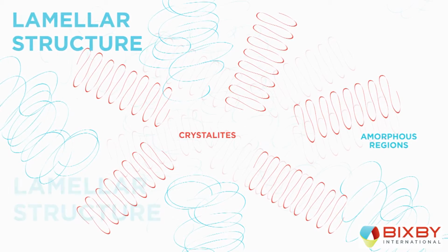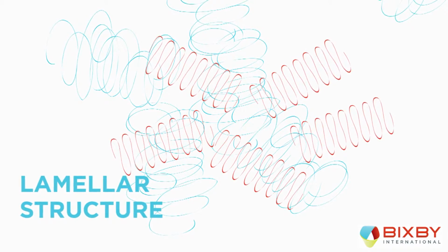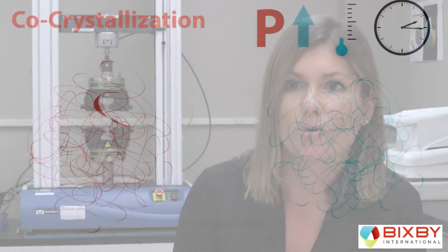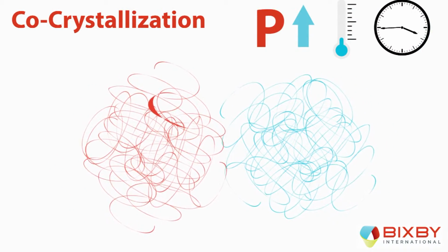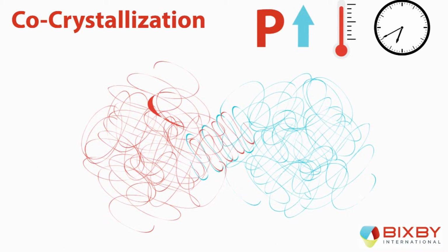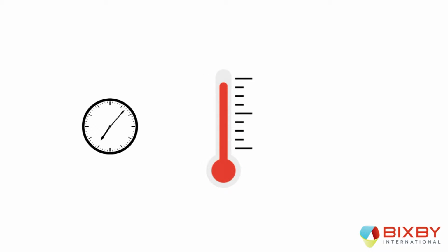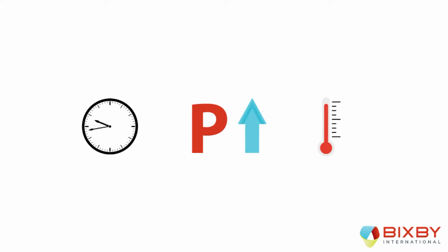There are a few variables that we can control to improve diffusion during the extrusion lamination. We can use a higher melt flow index, or in other words, reduce the viscosity of the polymers so the polymer chains have more mobility to freely flow and diffuse between each other. Increasing the pressure, the temperature, or the time in which the substrates are in contact will further improve the adhesion. Similarly, the variables of time, temperature, and pressure can have beneficial effects on the other bonding forces as they're increased by allowing greater molecular interaction.